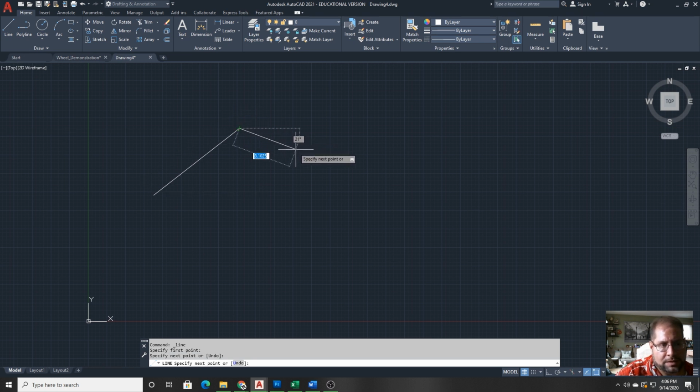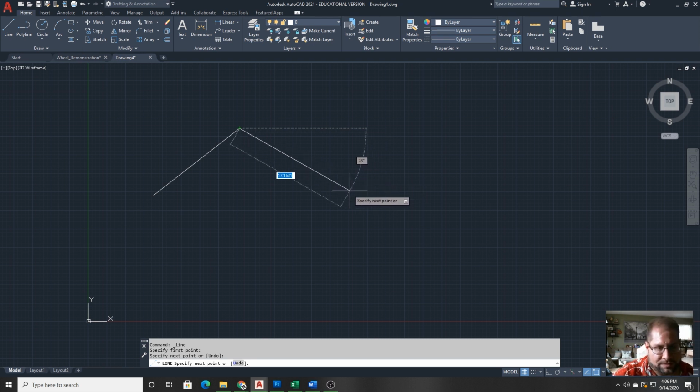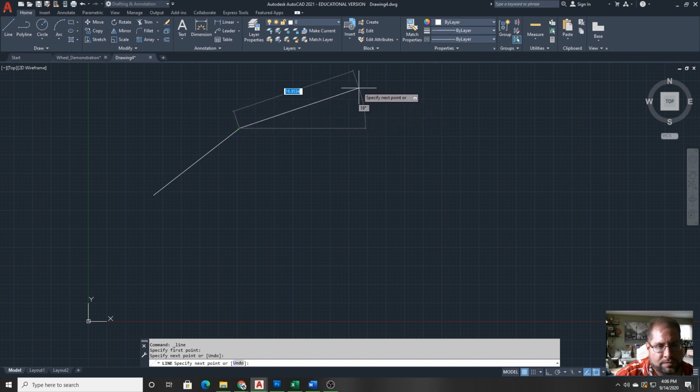As you can see, it automatically started drawing a second line from the previous endpoint of the first line. And again, I have more options on the screen as far as where to put that, as well as observe that there are some guides that pop up. So if I wanted to draw the line in a horizontal way, I could just move the line towards that particular area and it will highlight, and I could actually snap onto that.